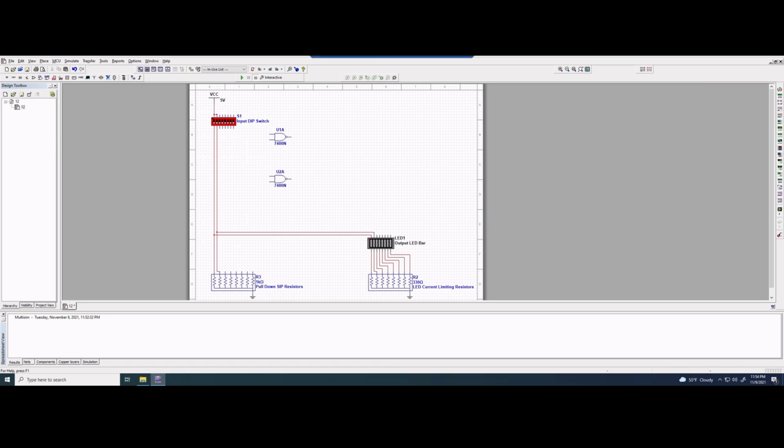Now we need to wire this up. So our Q naught is going to be on the bottom, and Q naught is going to be the very back, and then our Q is going to be right in front of it. Now we know that we have some wire going from our Q, the actual input. It's actually coming from our Q naught. So we can wire this in here like this, and then we're going to have the same thing for this Q naught. We have some input from our Q like this, and now our S is going to be the first thing connected right here, and then our R is going to be the second one connected right here. So this is what our circuit should look like, and now we can try testing it to see the truth table. So we'll run it right now.